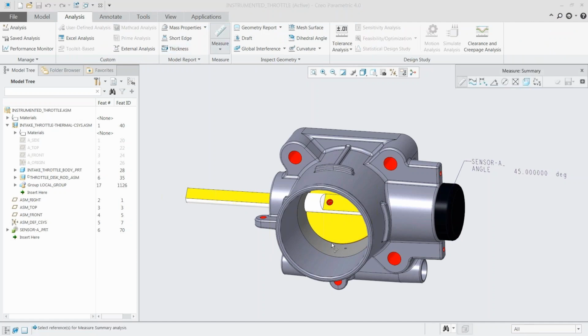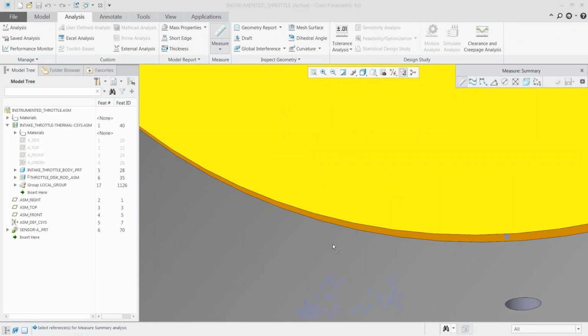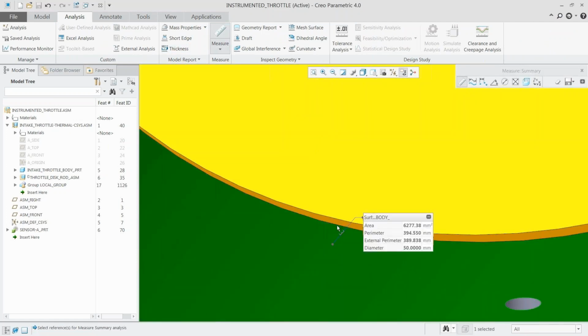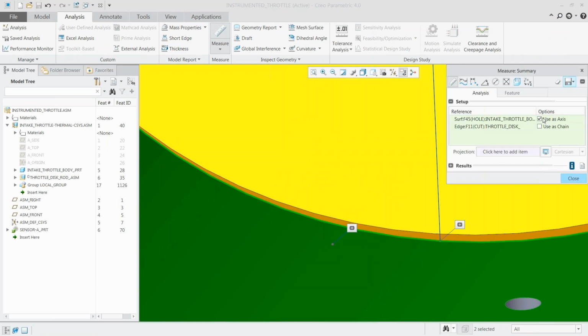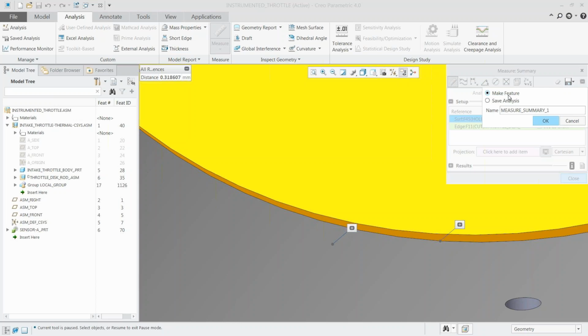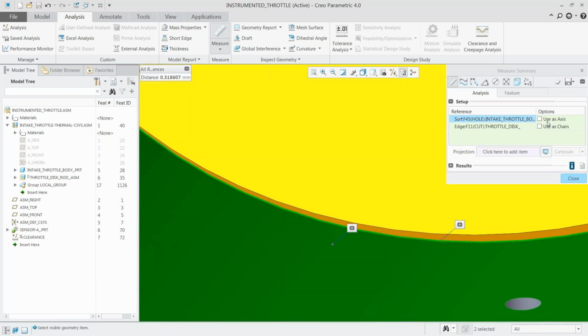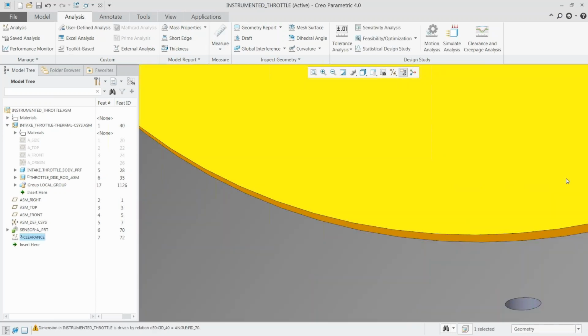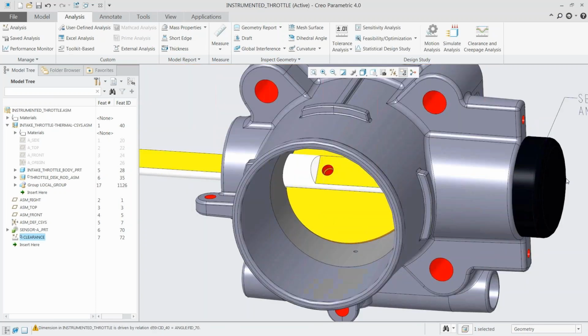Now, something else we might also be concerned about or maybe finalize, if my model is actually going to work, there's a clearance value that we care about. So when the temperature changes, the size of this disk and the size of my whole model might change under the stress that that's going to induce. So I want to set up an analysis feature that we're going to call clearance that is always going to be looking and measuring this particular point in the model. And I'm going to look at that later on to use that as my validation for my design.